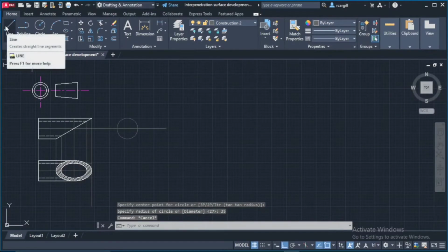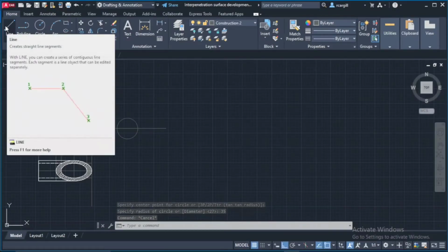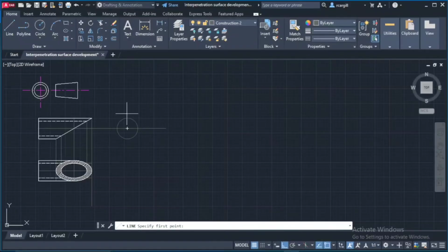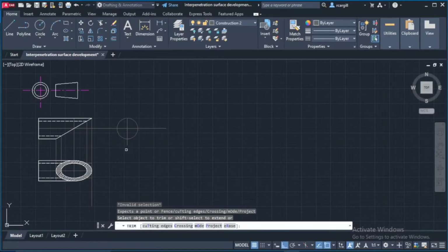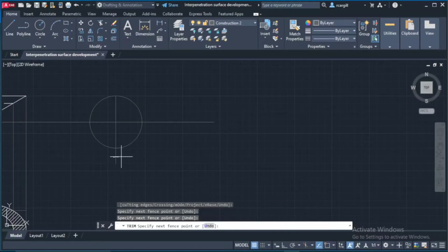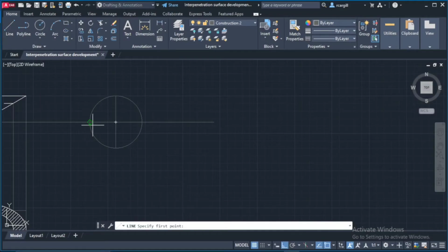So I'm going to divide this circle into 12 equal parts. To do that, I'll select a line from this quadrant here down to the next quadrant. Let me actually trim off that extra piece because I want it to be nice and clean for when I do my array. I don't want anything hanging outside of the circle, which is why I'm also going to draw a next horizontal center line, even though I already have one, and this is why.